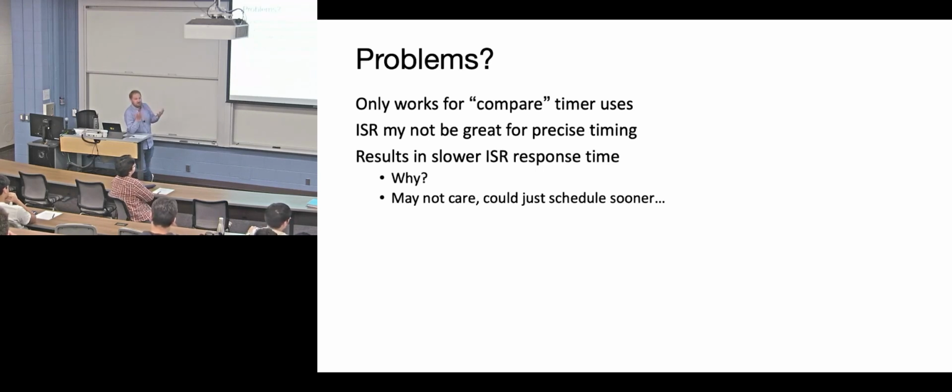Plus, you're going to have some software overhead, because even if it's less than 100 lines, it's going to consume some amount of time. So it's very hard to do precise timing with virtual timers. You have to have this mental division: precise things that need to occur happen with hardware timers, and imprecise times can happen with software timers. But for long-term human scale things, it's not really that important.